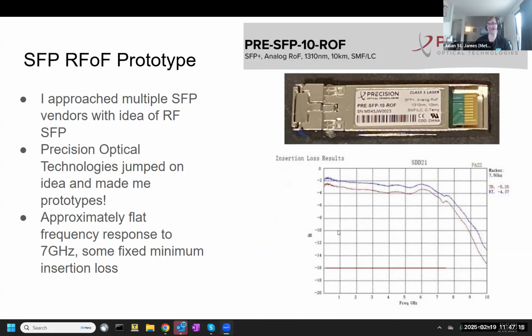I would say it has the same security and crosstalk issues as you would with a datacom link. As long as you have wavelength separation, it would be fine. I don't expect crosstalk, because this is a 1 gigahertz signal modulated onto a terahertz laser. As long as you have the terahertz separation, you should be fine.